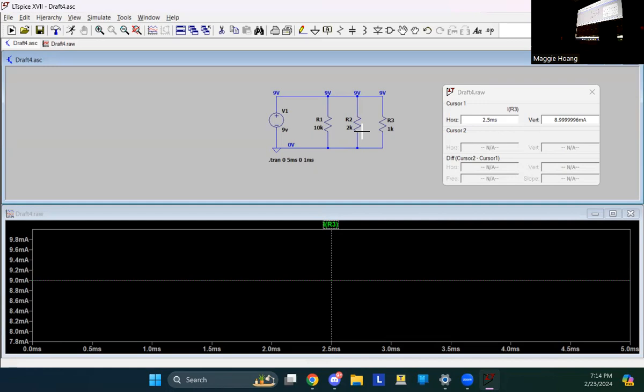Their slopes weren't matching up to their theoretical or measured ones, so I had to tweak the resistor and capacitor values. By changing those, I'm changing where the best frequency is. I do a lot of RF at work, so I'm changing how good it is at each frequency. It's just tuning the circuit, but I had to simulate it and that's what they wanted. So yeah, I use LT Spice.